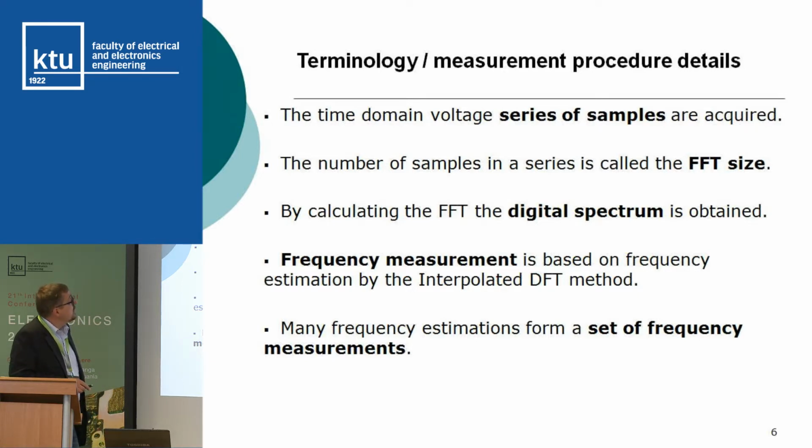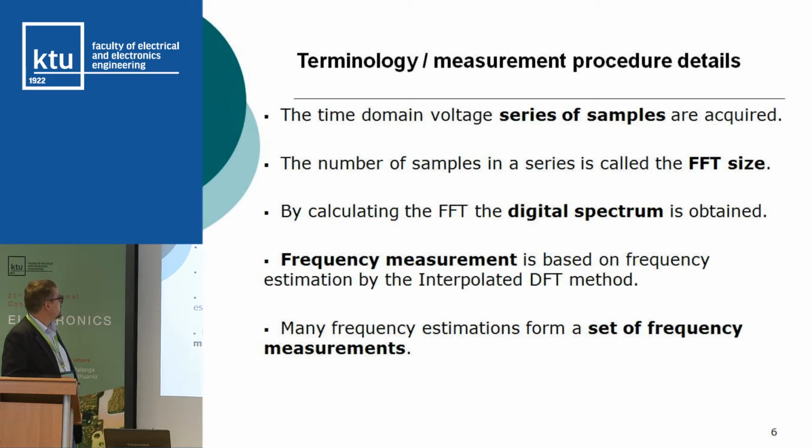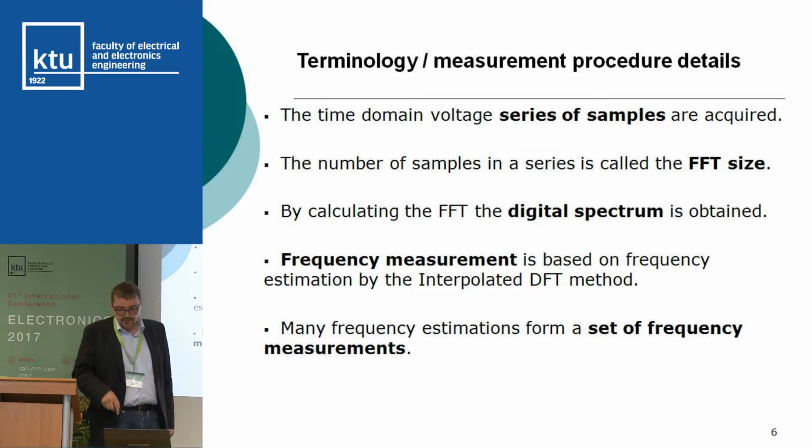Then an FFT is made and a digital spectrum is obtained. After using the interpolated DFT method, the frequency is estimated, and many such estimations form a set of frequency measurements. So we have two different kinds of samples, voltage and frequencies, and two different series, but I will always call the first one a series, and the last one I will try to name only a set of frequency measurements.